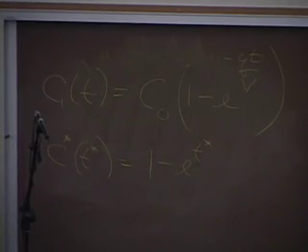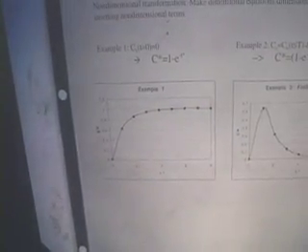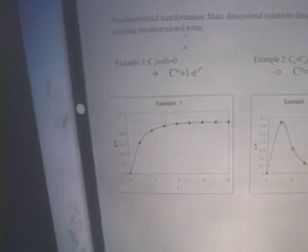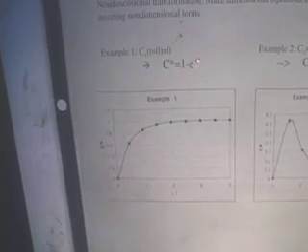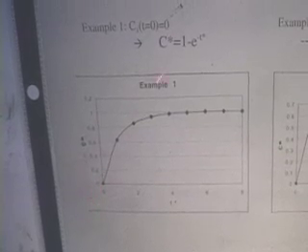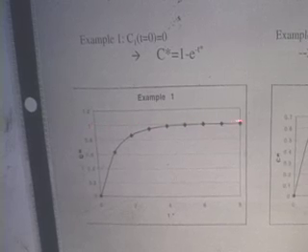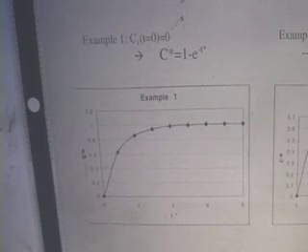Do you see, I can make a plot of this, t star versus C star, without telling you what? Do you have to know Q and V to make that plot? No, you don't. You have one plot. It starts at t star equal to 0, C star is equal to 0. As t star goes to infinity, C star approaches 1. That's dimensionless.